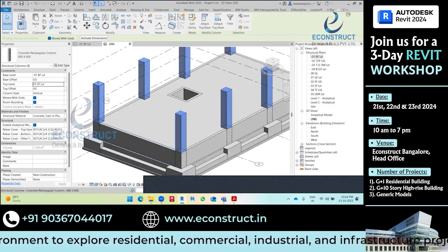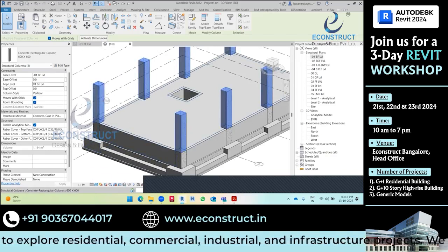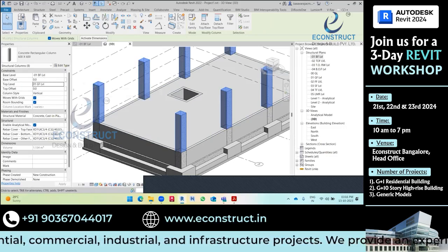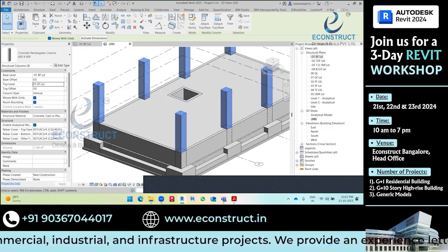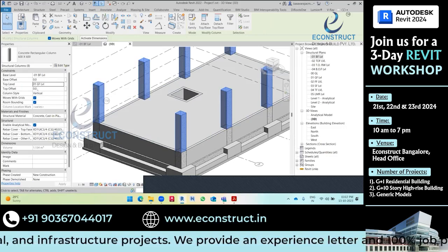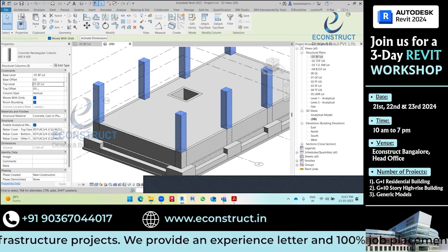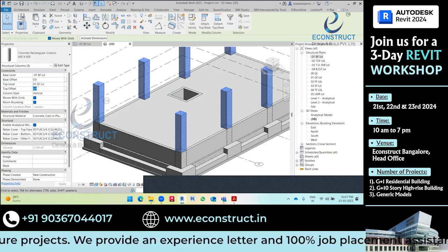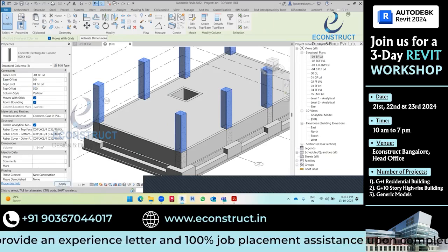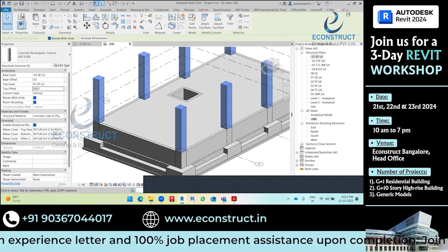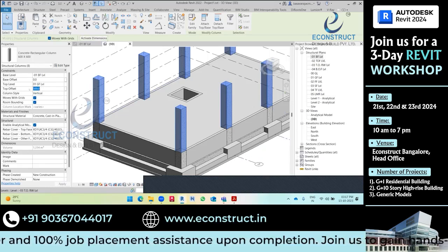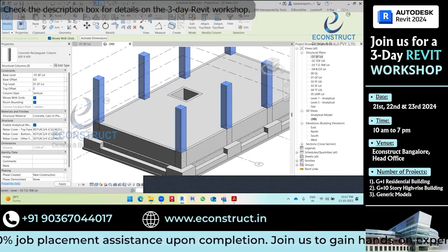and we have given the constraints also. Bottom constraint is basement floor level. Top constraint is ground floor level. Sometimes we want to give the top offset also. If you want, you can give a top offset like some 500 mm. If you give it, it will apply the top offset. I don't want to give any top offset, so I will make it 0.